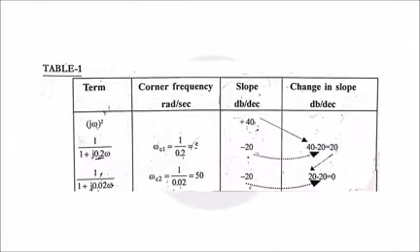We have studied in the previous class that when the numerator is a derivative term, it becomes plus 20 dB per decade. For the nth order derivative, that 20 dB is multiplied by n. So here I have j omega square, that is a second derivative, so plus 20 dB into 2, that is plus 40 dB.